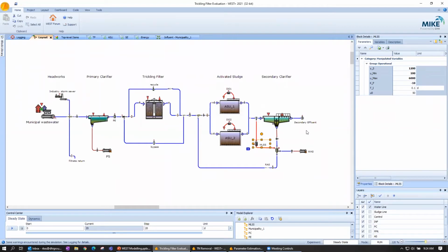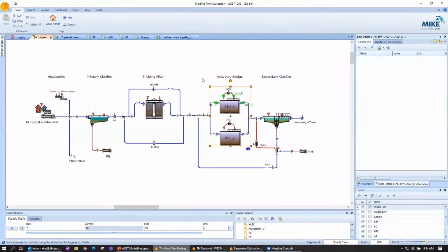But the nuance comes into the because part of the statement. So why do we think that this is feasible? And start to lay out some of the assumptions that we've made in this model that are going to need to be checked. So if I increase SRT, I'm going to have nitrification. Well, I know that that's going to require more oxygen. Is this model even set up to evaluate aeration rate?